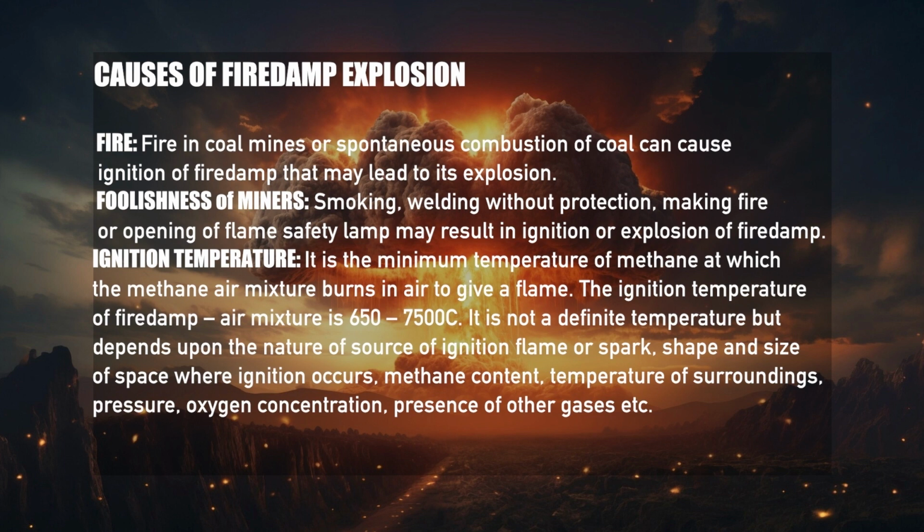It is not a definite temperature, but depends upon the nature of the source of ignition, flame or spark, shape and size of surroundings, pressure, oxygen concentration, and presence of other gases. If inflammable gases are present, then the ignition temperature becomes low. If there is presence of non-combustible matter, the ignition temperature becomes high.